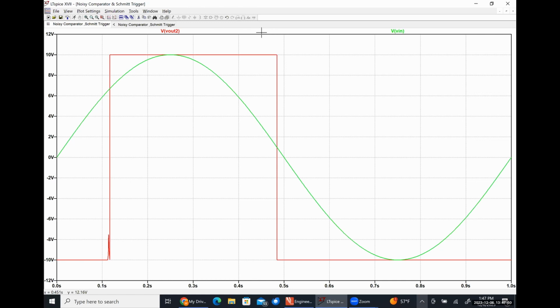So even if we ground it, we're effectively comparing things to zero. We're always comparing V out, V in, because we're trying to figure out the sign of the differential voltage, which is going to tell us whether the output goes high or goes low. Is that V in, so V plus minus V minus.